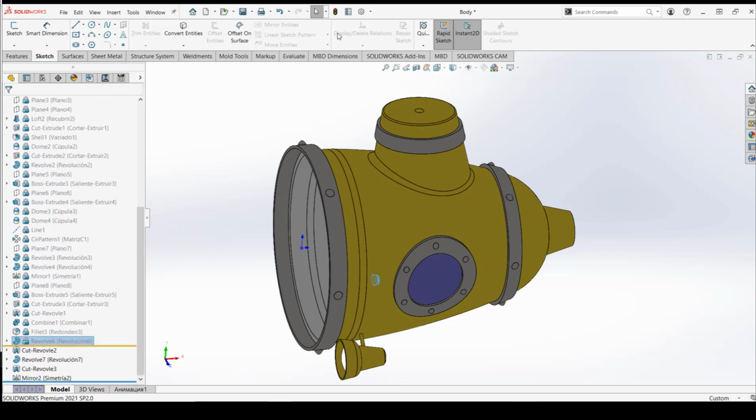And also when you rebuild, it will no longer rebuild those items. We're basically telling SOLIDWORKS, like, we're not concerned with modifying these anymore or rebuilding them. We're only focusing on the features below the freeze bar. So that's definitely good if you have a large model and your SOLIDWORKS is running slowly.